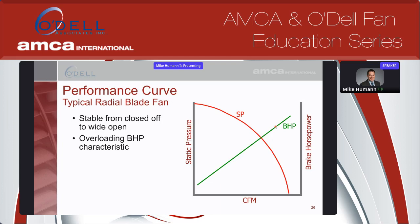So that's certainly something to know, because if you overshoot your static pressure requirement, and let's say you sized it for 20 inches, but you only really need 15 inches, you're going to move down the curve to where you only need 15, because that's where the fan's going to go based on the system curve. And your horsepower is going to drastically increase. That's an overloading brake horsepower characteristic, and just something to keep in mind when motor sizes are being selected for radial fans.